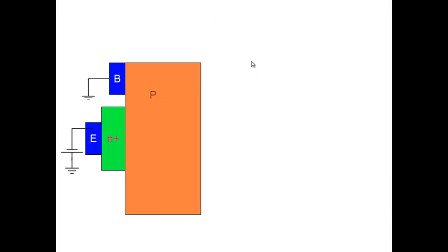Okay, so I've taken a PN junction diode, right? Just turned it to 90 degrees here. So I have a diode here, N plus P here. So this is a diode here. I've made a contact here and I made a contact here. Now in this particular diode, note that I have forward biased this particular diode. I've applied negative voltage here, and ground here. So when I apply a ground here, the voltage here, which means that the P-type, the voltage here, ground, will make all this region equal to zero bias here. All this region zero bias here, and this region would be, let's say, minus 0.7 or so. So at this junction, I have an effective voltage of, let's say, 0.7. Okay, so it's forward biased.